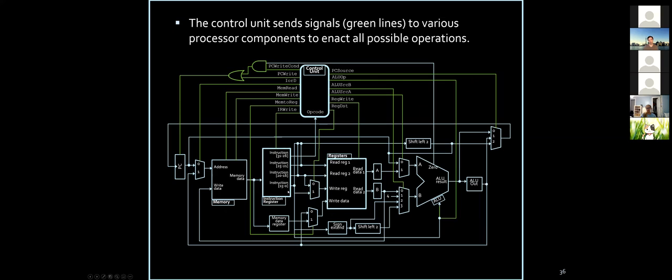So we can tell the mux to do something, like read or write, depending on this signal, source B, source A, and so on. This is exactly how it operates. For example, these two green lines go into the mux unit that then goes into our ALU, and they can turn it on and off depending on what we want to do. So this is how we orchestrate. There is no real black magic here.